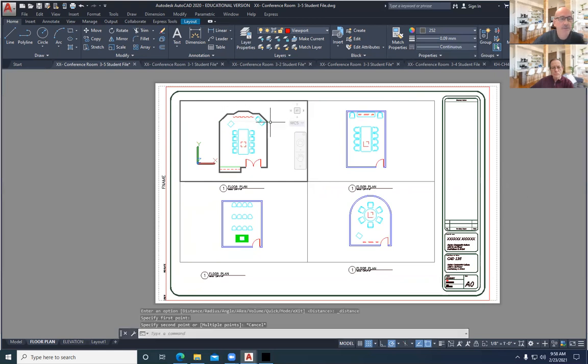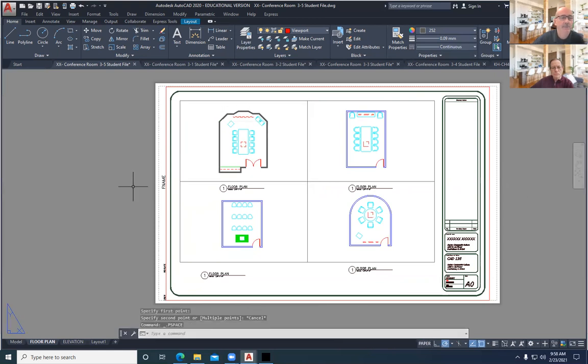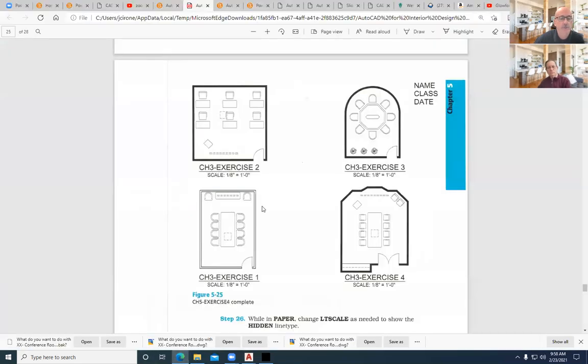Versus when I'm in paper space, and if I want to measure something, now we're looking at my title block, and we're probably more like 17 or 1 foot 3 inches, so 15.5 inches. That's how that works. Paper space is the paper, and the viewports are windows into model space. And so what you can do is you can create that drawing like they've done here for that.